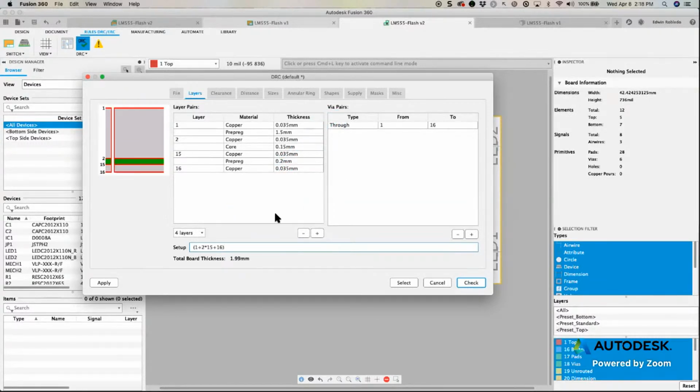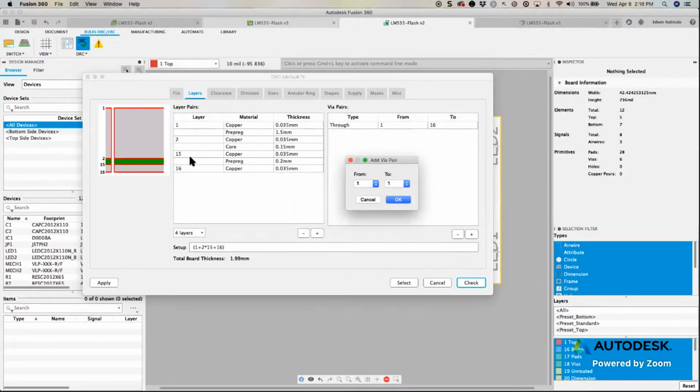So here I'll click on the plus sign, and I have a 4-layer setup here, as you could see. It gives me my layer list. I could travel the distance of my vias. Remember, what we're defining here is our vias. So let me explain what a via is. A via is the point of transition that a trace will make to travel the signal from one layer to another layer. I just want to make sure that everybody here is on the same page. I'll show that on the board in a minute before we continue going with DRC.